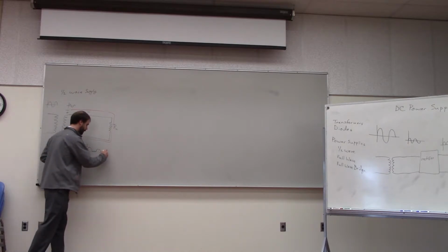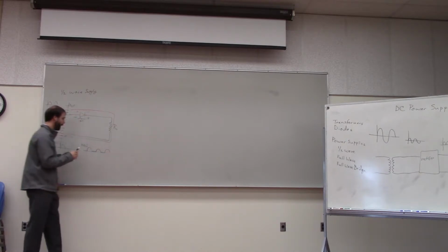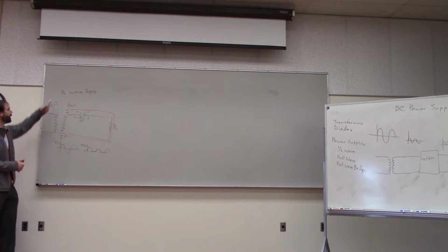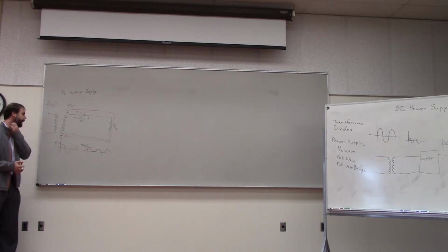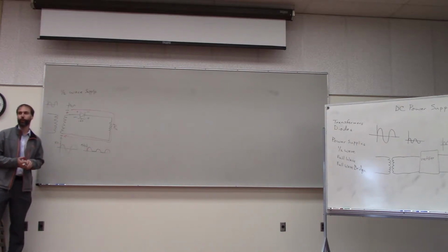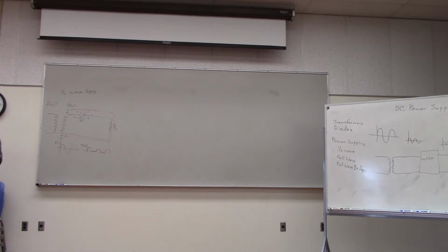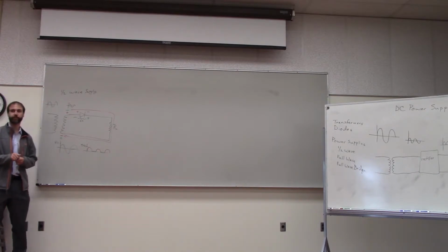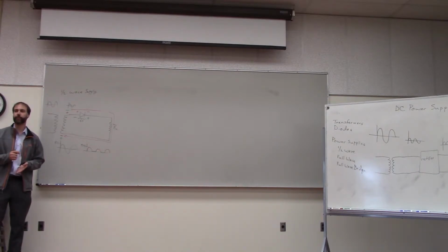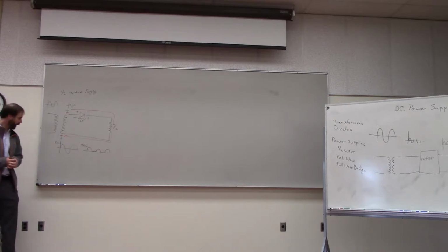So now you guys can see why we call this a half-wave power supply, because it only captures half of our input. Does anything happen to the negative part of the power? No, it just doesn't get used. It just gets blocked out by the diode. What would this type of power supply be used for? Great question.